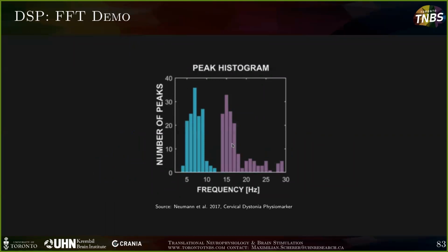So now, as I promised you, I have brought you these PSDs from a couple of papers. In this PSD, you can see there's a high frequency peak at the 7-8 hertz mark, and at 17 hertz. That means whatever signal was investigated there can be represented to a large percentage by a sinusoid which has an oscillation rate of 7 hertz or 17 hertz, encompassing a large quantity of the signal observed there.